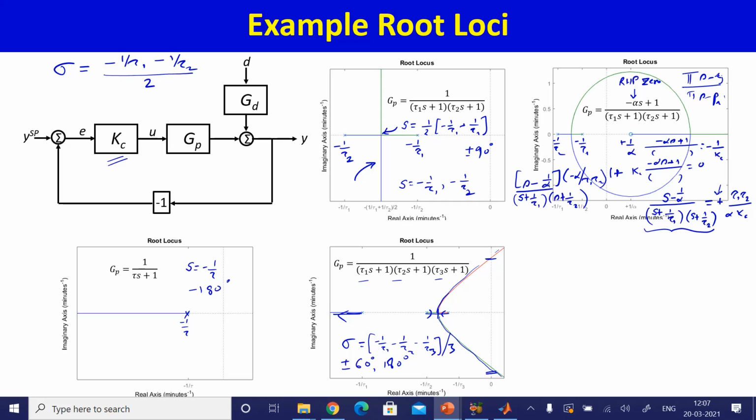And why this has happened is because of this right half plane 0 that creates an extra negative sign, and so the negative sign on the left hand side and the negative sign on the right hand side actually cancel out, and so what you get is g, the loop transfer function, must be equal to a positive real number, and therefore the angle condition for this example will be that the angle of g must be even multiple of pi, plus minus even multiple of pi.